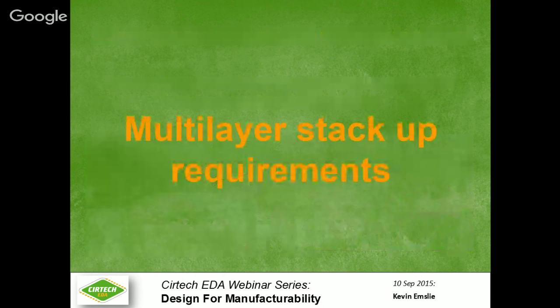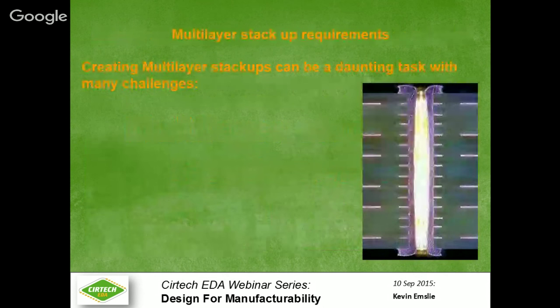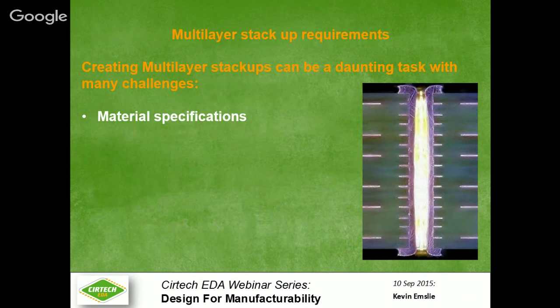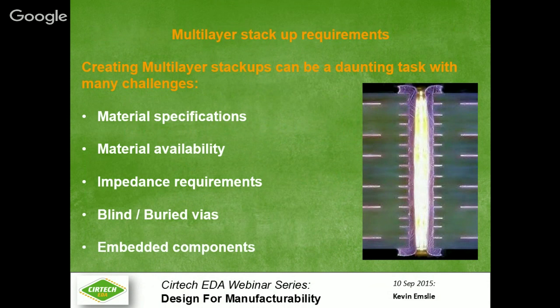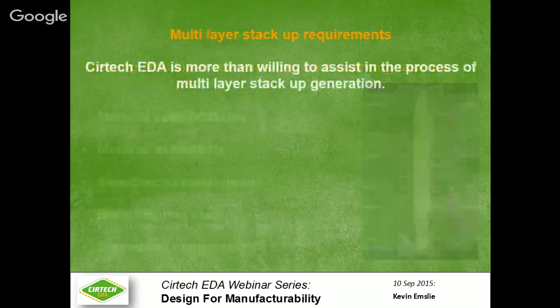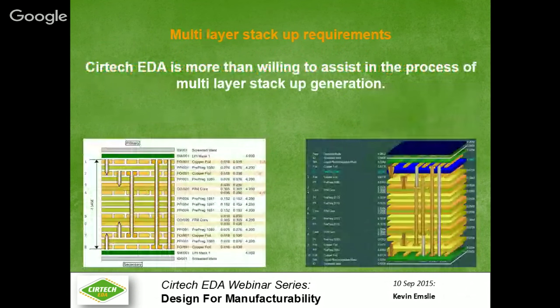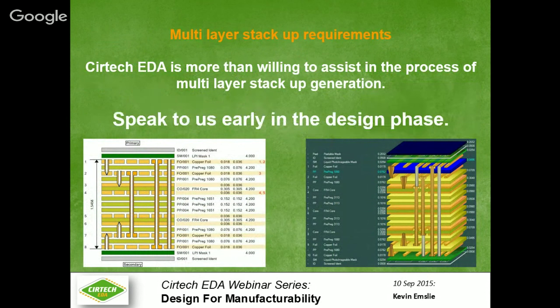Okay, multi-layer stack-up requirements. Creating a multi-layer stack-up can be a daunting task with many challenges. For example, material specifications, material availability, impedance requirements, blind and buried vias, and embedded component requirements. Once again, Certec EDA is more than willing to assist in the process of multi-layer stack-up generation. We can help you to choose the right stack-up for your design. But please speak to us early in the design phase. We can set that in stone early, and that'll help your design process.